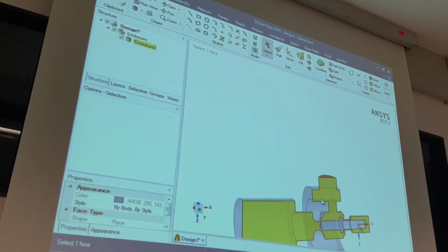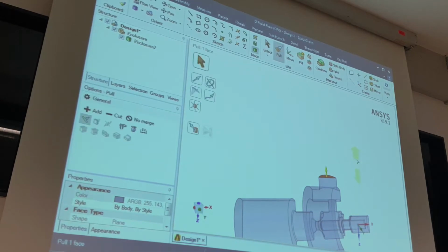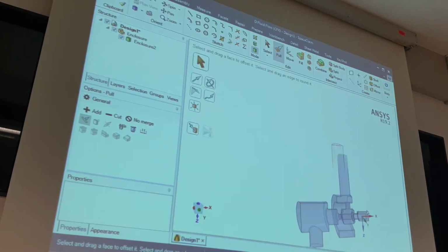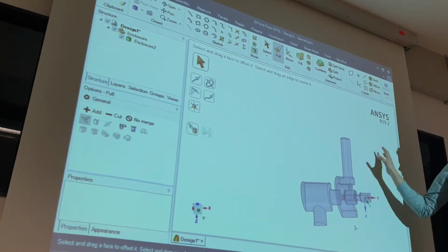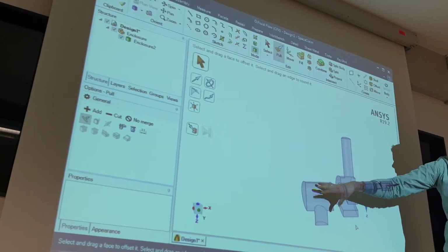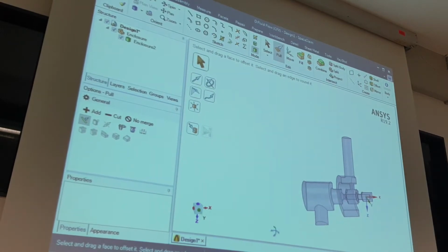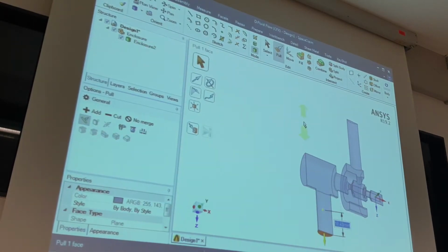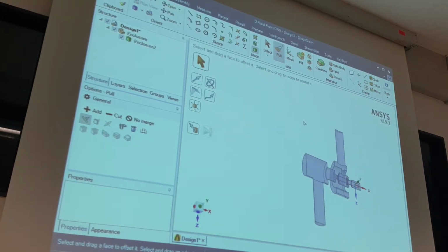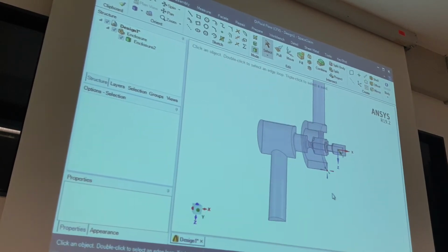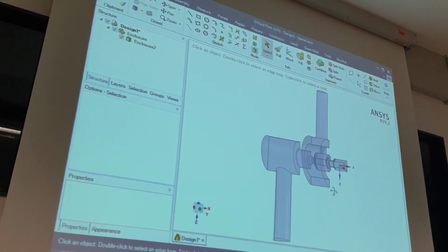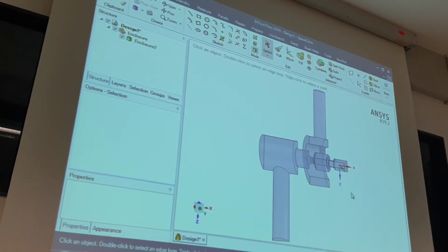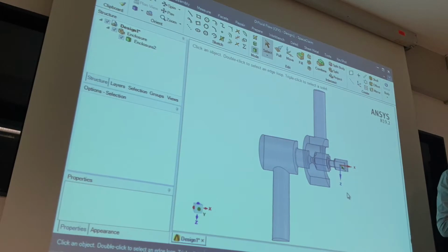If you see visually that it is long, then it depends on other parts of the geometry. So I use the pull function, 20 millimeters. It looks long, yes. It depends on other geometry. It looks okay, yes. It looks proportional, then it's normally enough. And here the inlet is also 20 millimeters long. So this is the second main thing. My inlet and outlet have to be long, to get correct results. Okay. And we did our geometry for simulation.